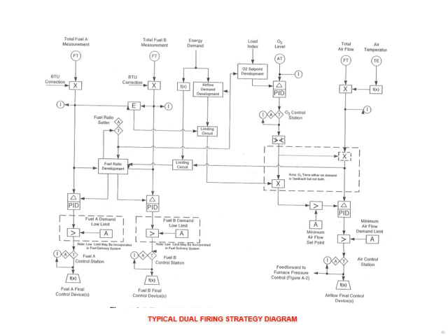If both fuels are following a boiler energy demand, then an operator adjustable fuel ratio setter determines the ratio of the fuel being fired. Unless both fuels are automated to follow the boiler energy demand, the fuel ratio setter will track the actual fuel flow ratio.